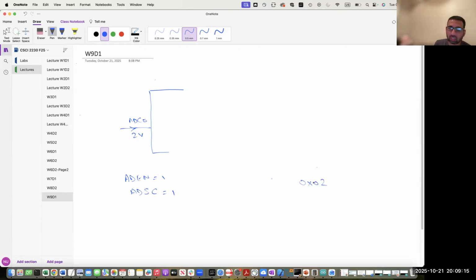So this will be placed in ADCH and ADCL, right? But how do you know that the conversion is completed? For that, you need to check the ADC interrupt flag. You will be continuously monitoring, reading it continuously. If this flag is set equal to 1, it means that conversion is completed.